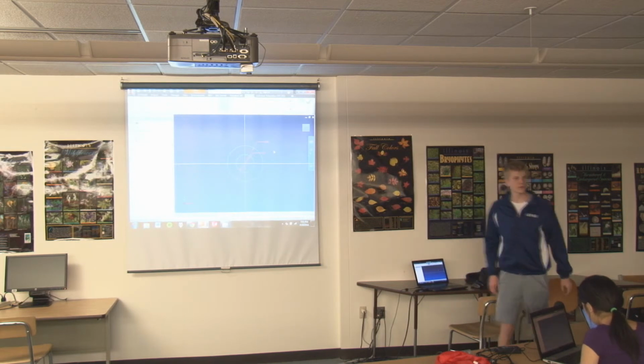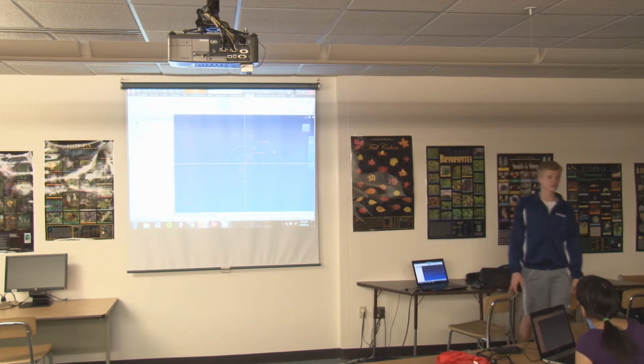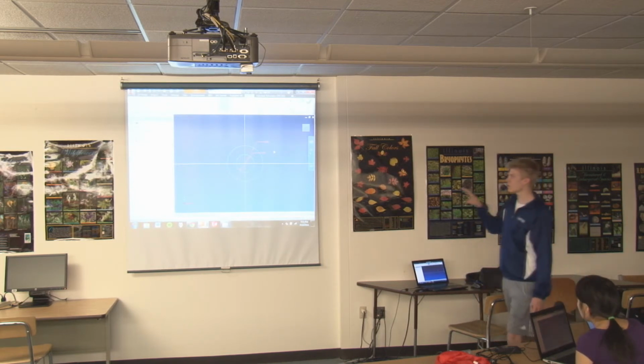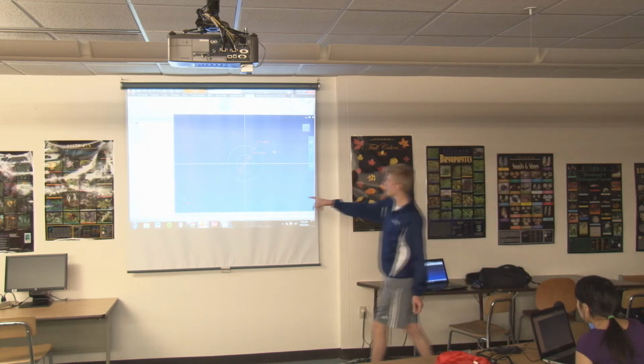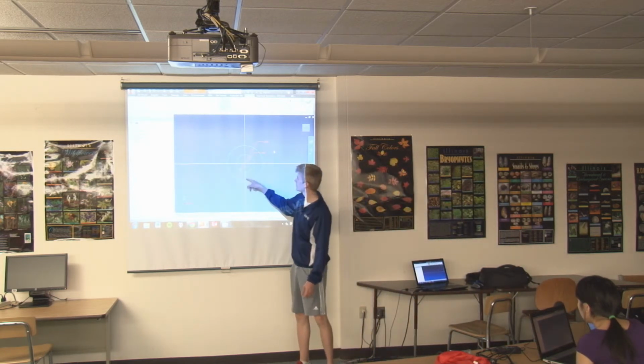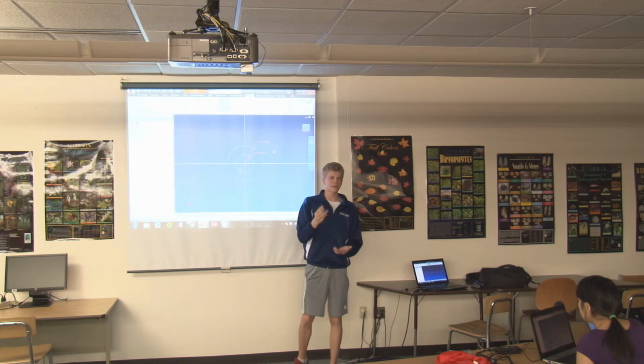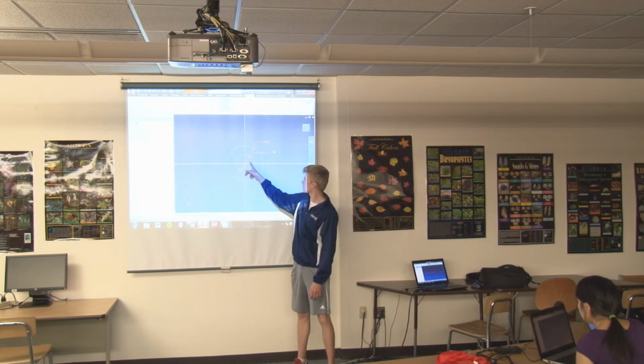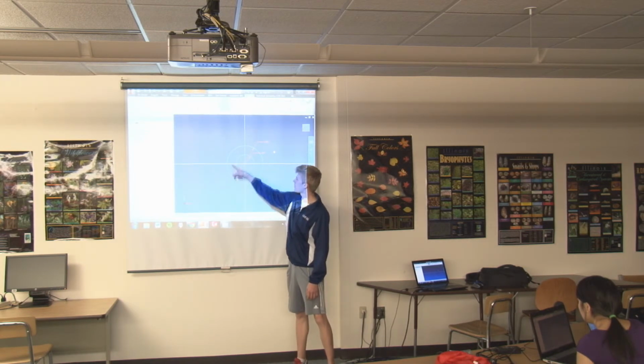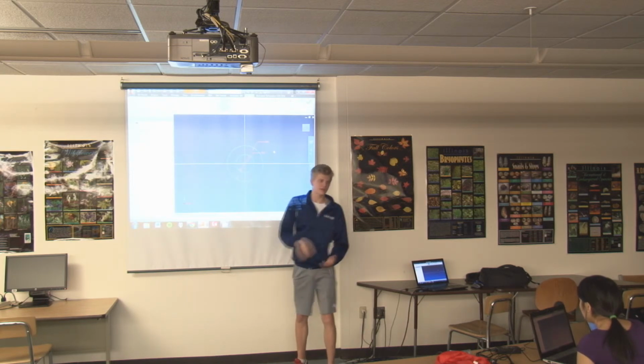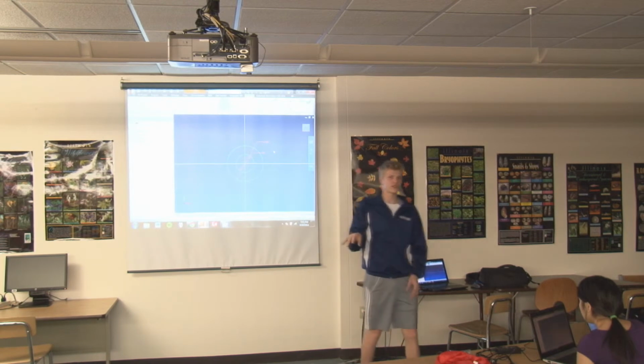Now, what you can do from here is actually one of the most useful tools. When you go to extrude this as is, if you were to create a hexagon within the circle, you'd have three separate points of extrusion. You could either extrude this inner circle, the hexagon around it, or the little space around the outer circle, because it just looks for completely closed off shapes.